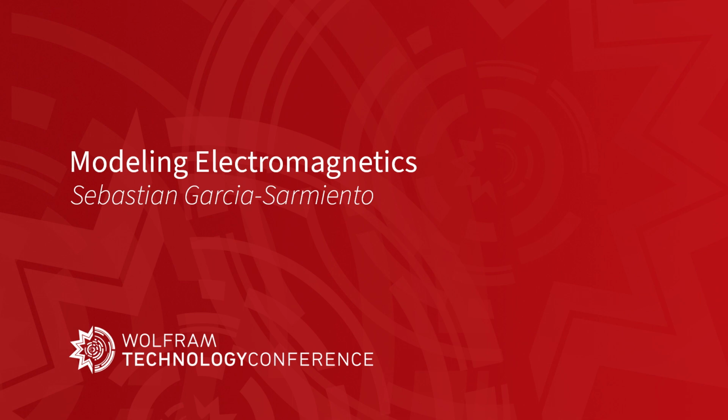I see that there is another question. I'm interested in antenna near field and patterns. Are there resources already available that you're aware of, or someone with experience I could contact? Antennas and near and far field patterns deal with electromagnetic fields. If it is a 3D model, we don't yet have the capability to simulate electromagnetic fields propagating in 3D spaces, because it needs these famous curl vector elements that we don't have yet implemented in Mathematica. So it may only be possible to simulate antennas and electromagnetic radiation if you simplify your model by going to a 2D domain instead of a 3D domain.